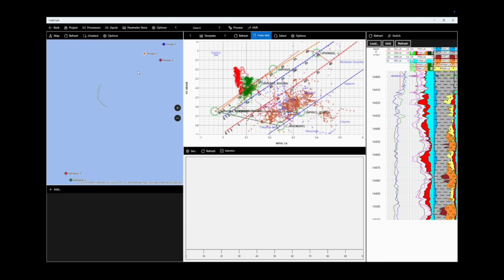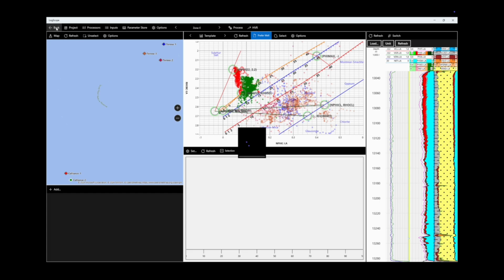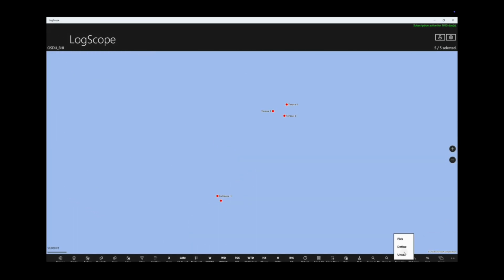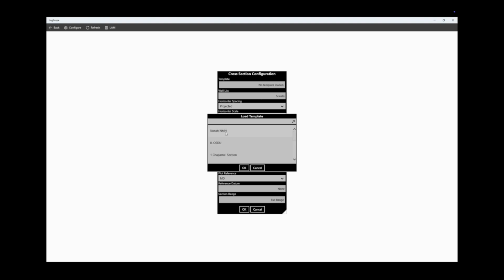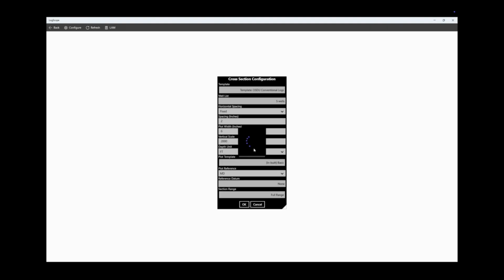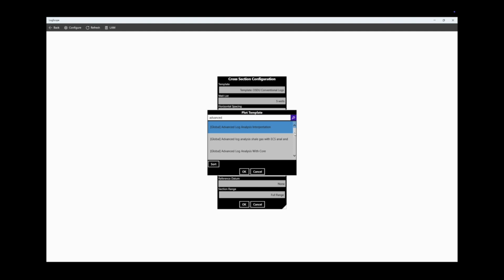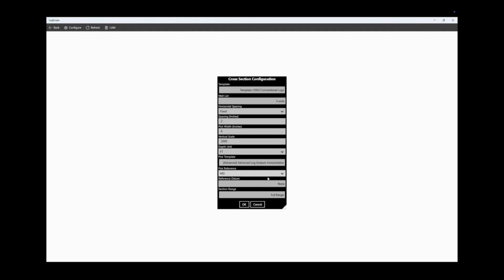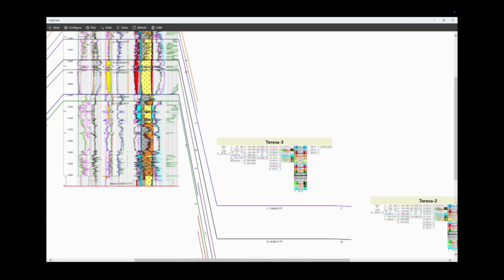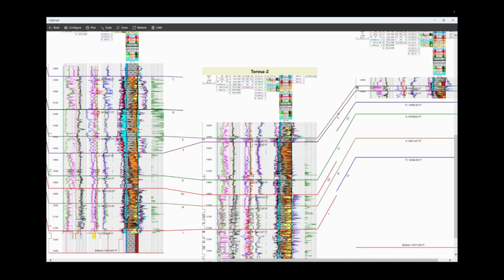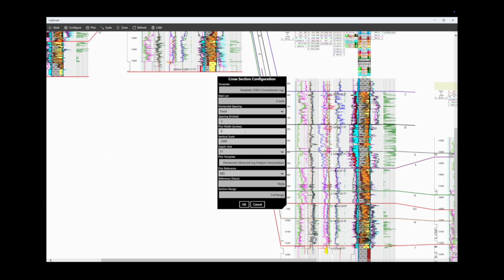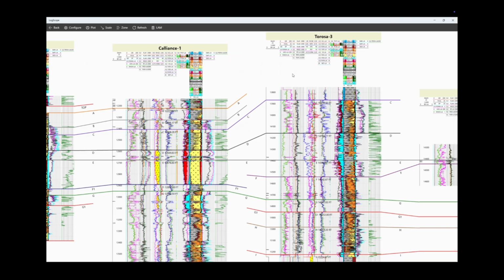And then as you can see we've got the results of each of the wells, and we then want to see what they look like in sections, so we create a section from southwest to northeast and we display it here. And as you can see, we've got the section, and we can move through the section and look at the wells, look at the intervals. We can also change it so that it's hung on a particular formation, so it's nicer to look at.